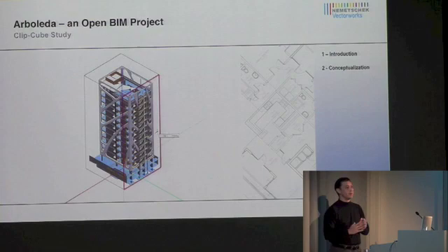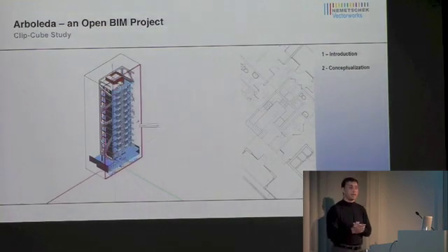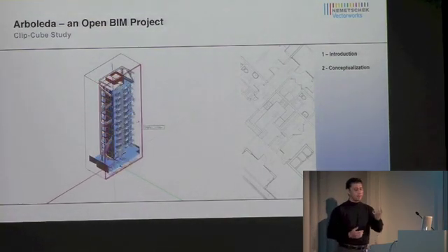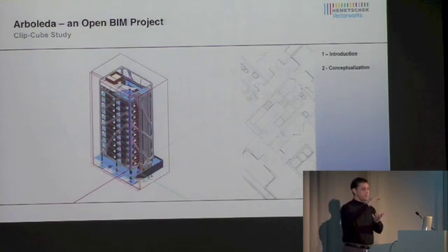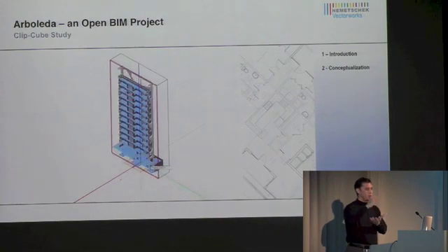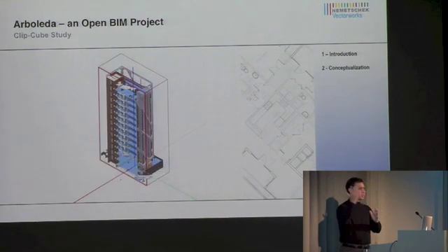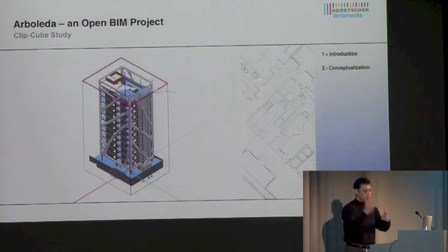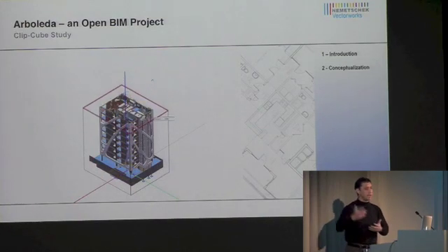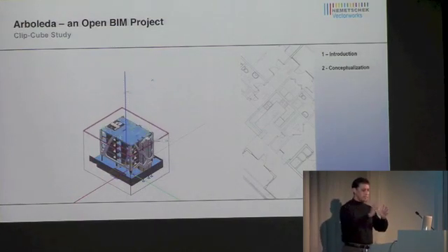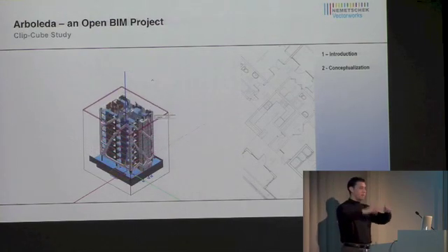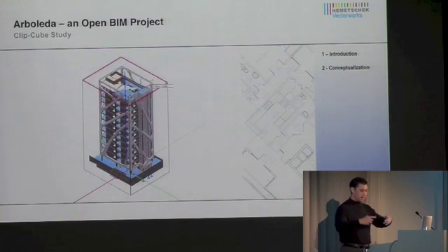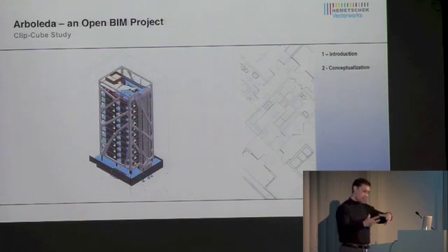Another piece that we had the opportunity to use is the clip cube. Now, I had to know that each one of these pieces, stories, was aligned one on top of the other. And instead of cutting sections and taking the time to just wait for the viewport to be rendered, I can use the clip cube and then make decisions, just push one of the faces inside the building on one side, maybe on top, and then quickly get a reference of how my project is going. And you can also rotate it and save that view.